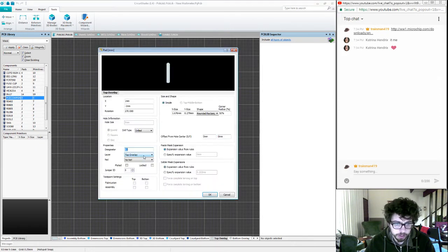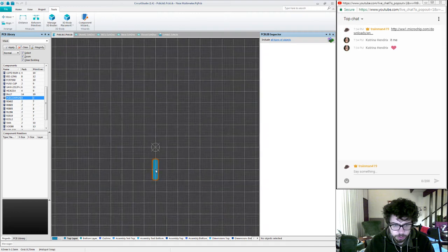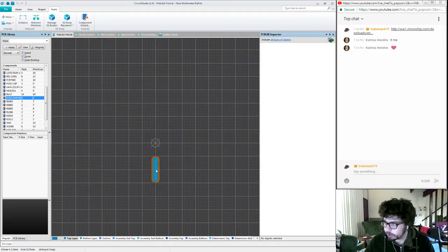I'm just going to do all these pads by hand because I can. We'll start with pad number 1. So this says Y1 should be 1.95, but plus 0.35 is 2.25. The other dimension is going to be 0.55. And I'm using a rounded rectangle pad because that seems to be the current recommendation in the industry. And so this was recommending fully rounded pads.